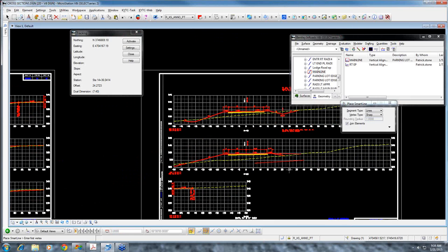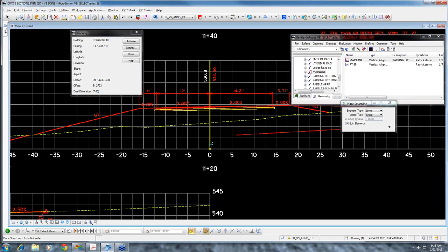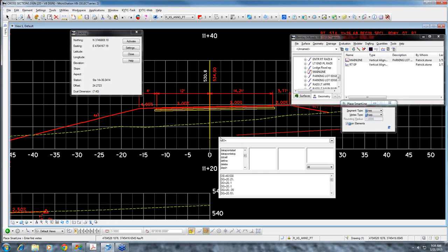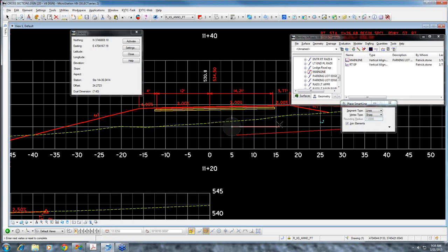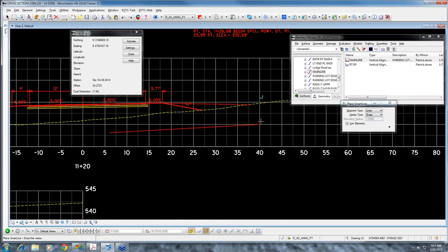So that's just a little something. You need to be aware of where the intelligence is on these cross sections and profiles, or you won't get what you want. Now, the delta offset, that's just delta from wherever you're at. If I wanted to go up 5 and over 5, if we clicked right here, we did a delta offset 5,5, it's going to put it right there. I may find that useful. I don't know if you're drawing in something, but I don't usually use the delta offset, but you might.